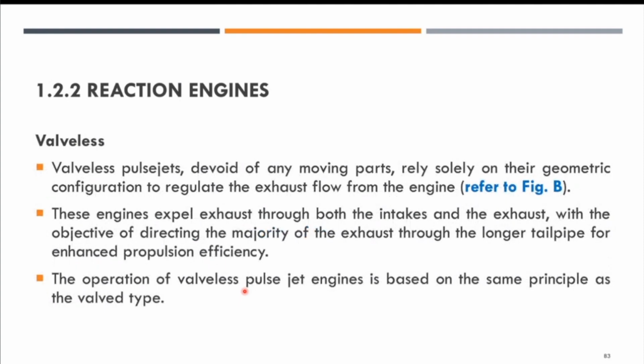Compared to the valveless, there's no valve involved, no moving parts, relying solely on their geometric configuration, as shown in figure B just now. And this engine expels exhaust through both the intake and the exhaust, with the objective of directing the majority of the exhaust through the longer tailpipe for enhanced propulsion efficiency.